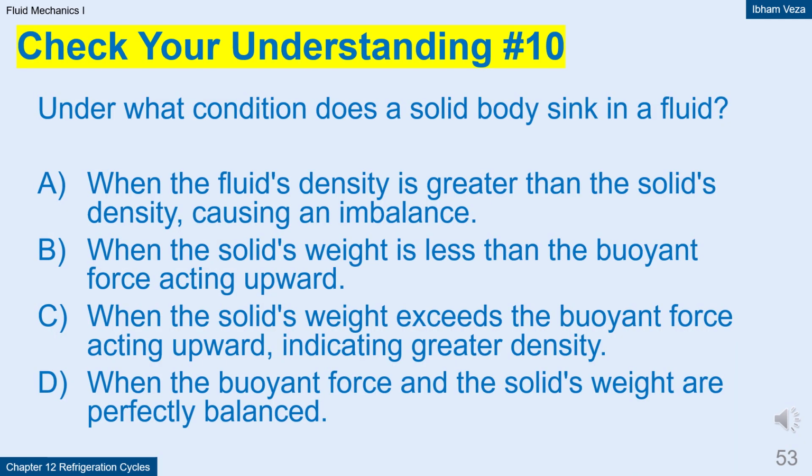Check your understanding number 10. Correct answer, C. When the solid's weight exceeds the buoyant force acting upward, indicating greater density. Explanation of incorrect options. Option A. This is incorrect because a solid body will float if the fluid's density is greater than the solid's density, not sink. Option B. If the solid's weight is less than the buoyant force, the body will float, not sink. Option D. When the buoyant force and the solid's weight are perfectly balanced, the body is in equilibrium and does not sink, but remains suspended or floats.